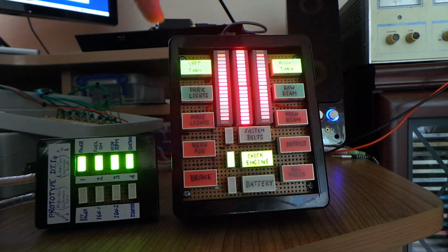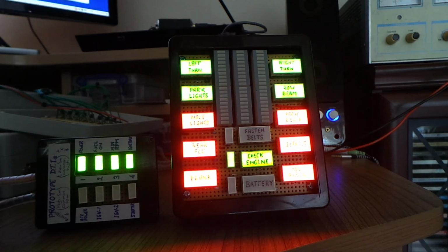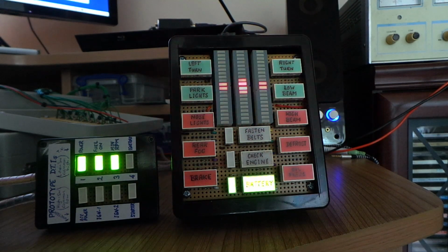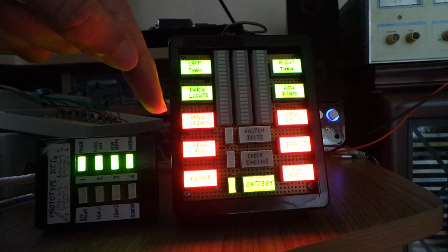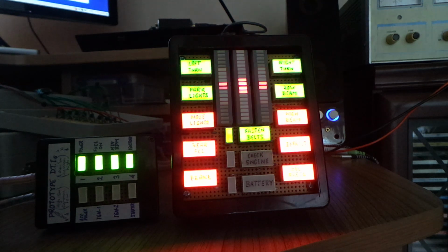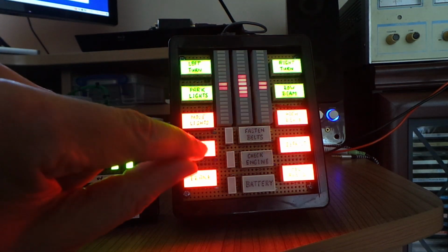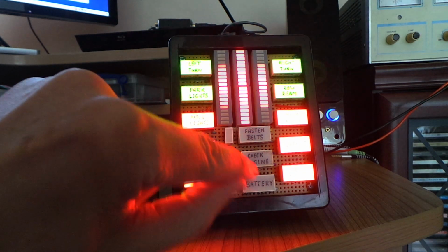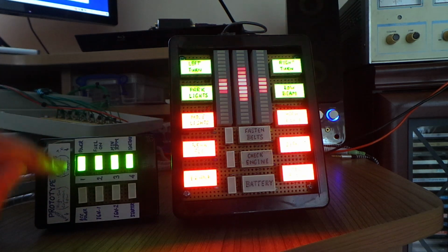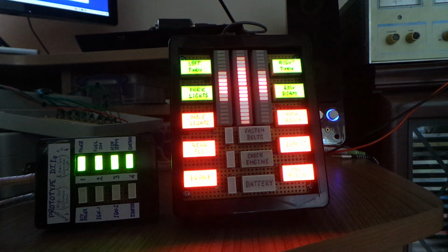So we've looked at now the non-functional mode of the side indicators, where they're all going in a show mode. We've looked at the non-functional mode where they're continuously on. Another press of the push button number 1, short press, will put us into a mode where only the normal auto pursuit indicators are functional. The dash top indicators and side indicators will remain on in this mode.